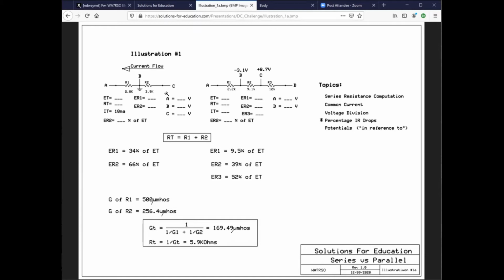If we ever get around to discussing inductance, reactance for inductance, reactance for capacitance, you'll find that everything we learn about coils and inductors, then we turn around and study capacitors, we'll find that capacitors are totally backwards or opposite from the coils. And guess what? Every combination, every circuit you learn where they have formulas, the formulas are all backwards. So when you put capacitors in series, this kind of a formula comes into play. However, you put capacitors in parallel with each other, well, then the capacitance adds.